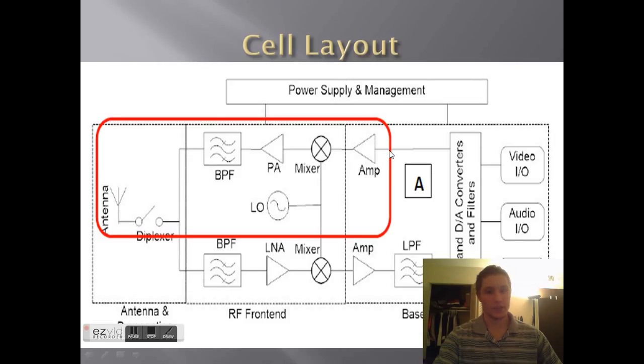The first thing I'm going to say is the signal right here is going to be a voice, which is going to be sent through an amplifier, which is then going to be mixed with a mixer with this carrier frequency, which is then sent through another amplifier, which is then cleaned up with a bandpass filter, and then finally sent out the antenna.